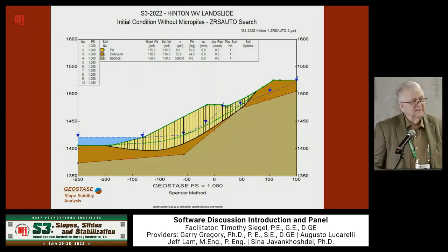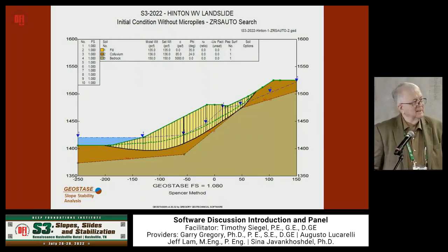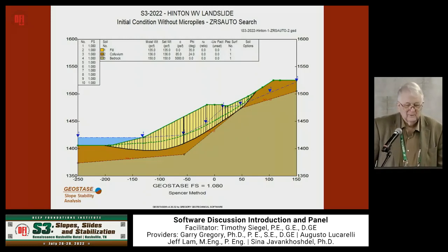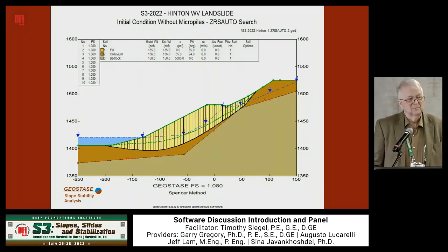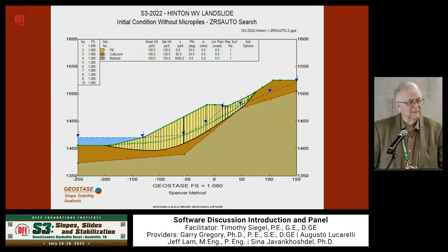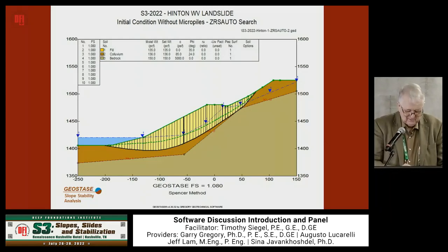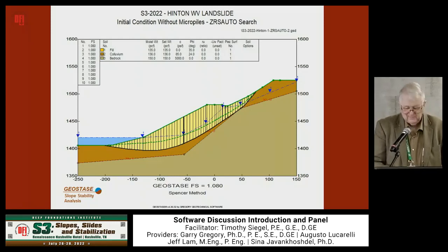Now it's failing, it's creeping based on the inclinometers and so forth. So with a creeping slope, rather than a catastrophic failure to start with, we would expect the factor of safety to be a little above 1. And in fact, George Sowers, I talked to him a lot about this, and he has some indication of it in his book. So we could remember that's factor of safety 1.08.